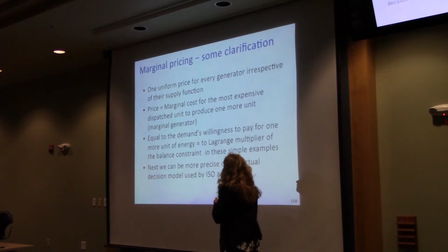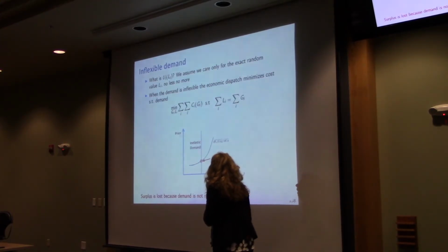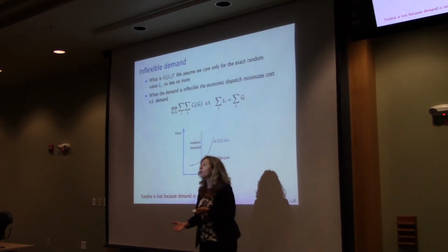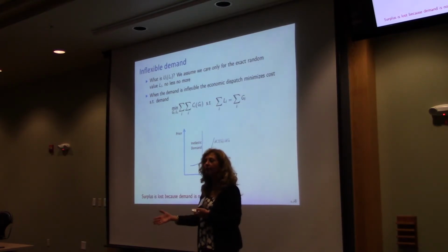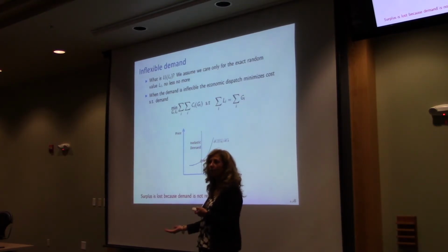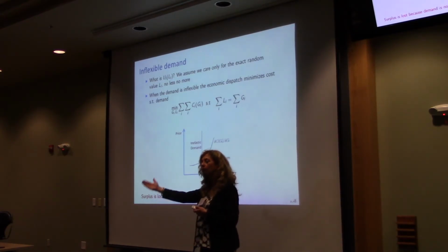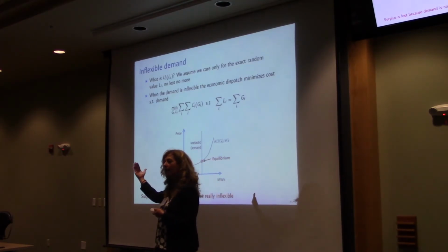All right. So now here I didn't put any constraint, but typically these curves don't last forever. You cannot generate more than the capacity of your plant, and you're not going to open your plant unless you have to produce at least a minimum energy. So there are constraints on the amount of generation you can actually have. So you will max out the cheapest generators, and then you will go to the next unit, and then the next unit, until you fulfill all the demand.